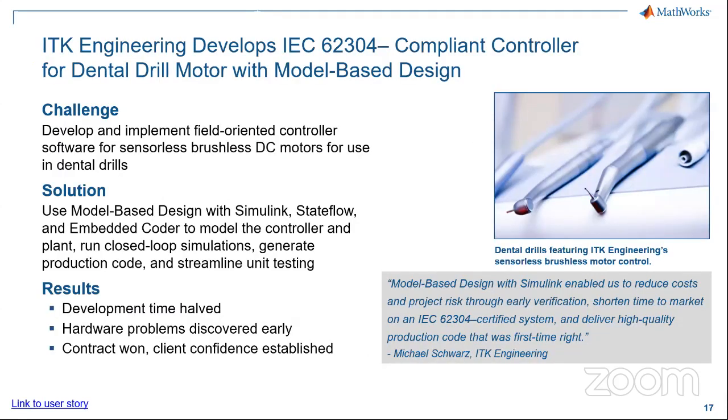And now this is an example of our customer's model-based design story. This is an ITK engineer, and they are part of Bosch. They needed to develop a sensorless field orientation control in their new brushless motor for a dental drill application. And one of the special things is they started modeling the motor and control algorithm even before the motor prototype was available. So basically they ran closed-loop simulation to correct issues on the controller side and generated more than 5,000 lines of C code by using Embedded Coder.